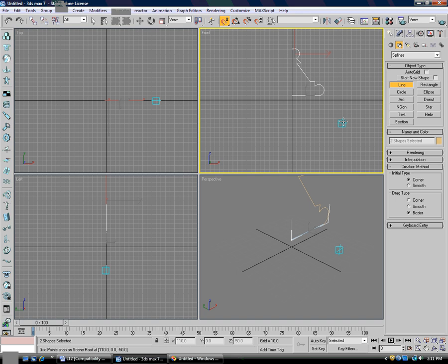If I rotate this half of the cross section by 360 degrees with the shading, you will get a three-dimensional pawn. To do the lathe operation, we have to attach all these components that we have created together as one object. So what I am going to do is go to the modeling tool.